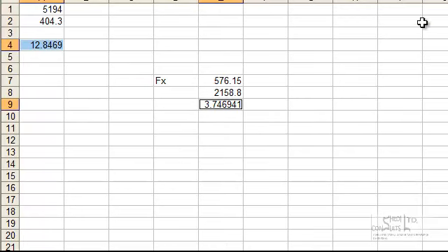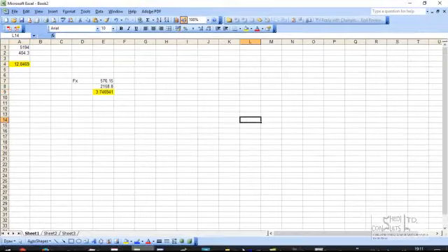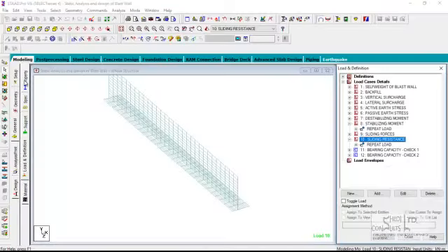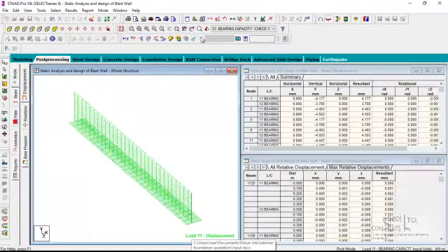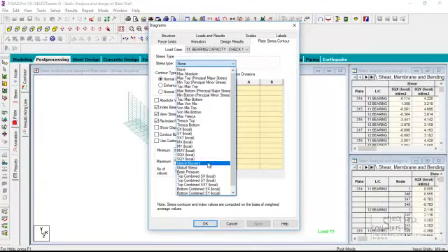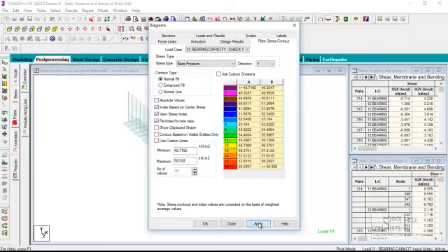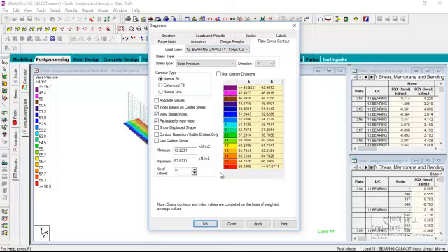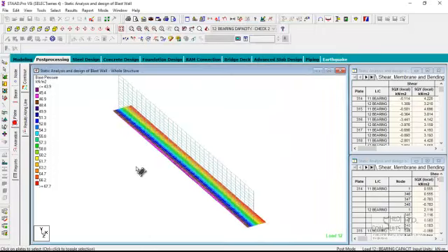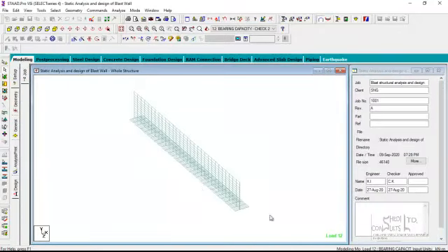And then when we looked at the bearing capacity failure, what we saw clearly showed for the various combinations. The maximum base pressure is about 58.9 under load case 11, and then 67.67 under load case 12, which is way less than the bearing capacity of the soil. So the structure is satisfactory.